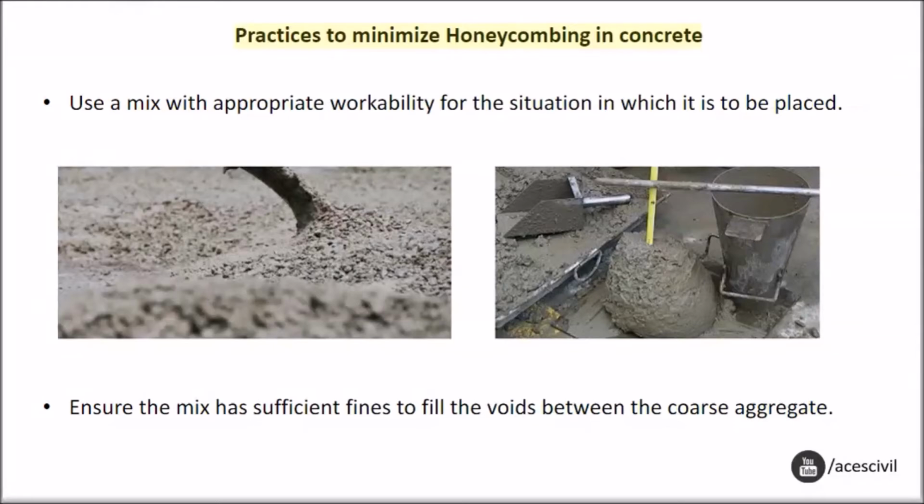Practices to minimize honeycombing in concrete. Use a mix with appropriate workability for the situation in which it is to be placed. Ensure the mix has sufficient fines to fill the voids between the coarse aggregate.